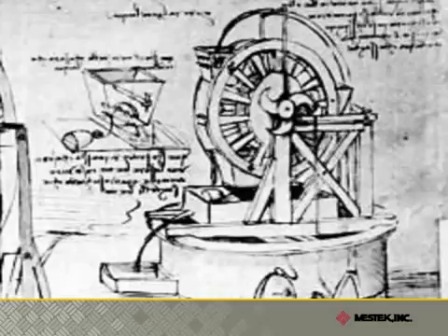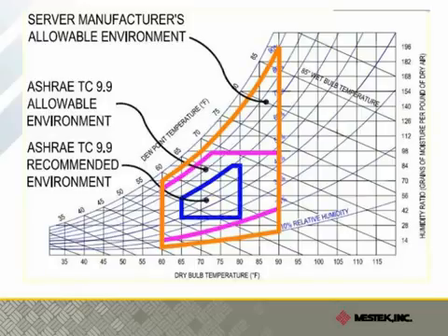The building and the contents of the building were cooler, and the same idea can be used to cool those thousands of servers without ever needing chillers or DX equipment. The reason this is now a viable alternative to conventional cooling solutions is that the world of server design has changed. Server manufacturers publish data showing that their servers work just fine with inlet temperatures of 90 degrees F and even higher for the newest state-of-the-art designs, and relative humidities from 10% to 90%.